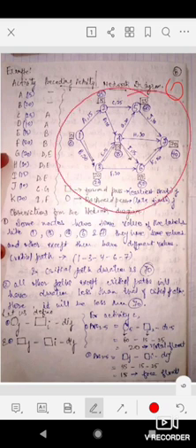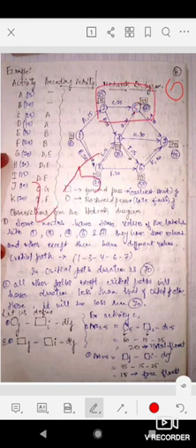So after making this precedence diagram and after showing the duration also at the nodes, you can calculate float. Float is the extra time which is available to us so that we can delay the project. We have here calculated total float, and this is for free float. How can we calculate total float? For total float, keep in mind the latest time at node 5, if we are calculating float for arc 2 to 5.